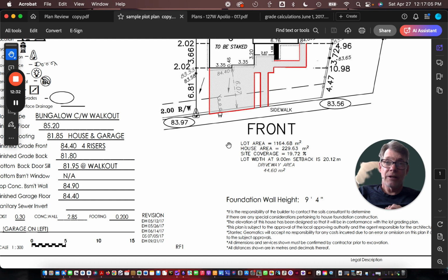So what we have here is a situation of a city that's been around for a couple hundred years, and some of our streets are pretty old. And in some cases what that has meant is that the sewer lines weren't buried that deep. Why? Because back in 1930, people did not do super deep basements, gosh, 5, 6 feet, whatever, below the ground, not super deep. And it was very easy to get that slope, no sense digging too deep. Nowadays, folks like to have deep basements. 8 foot is not even a thing. Almost everybody goes 9 feet. Some people go 10 feet.